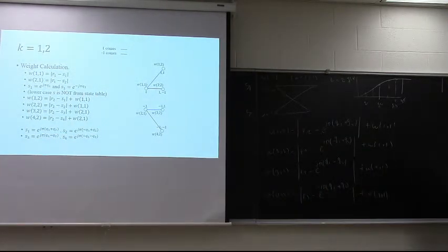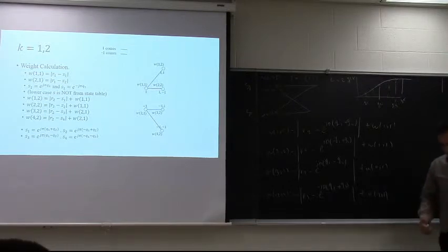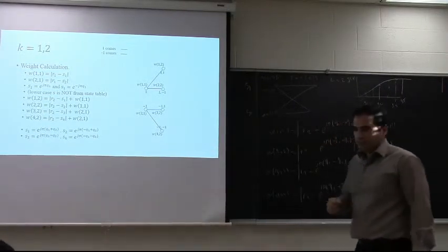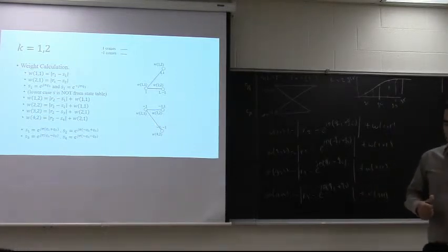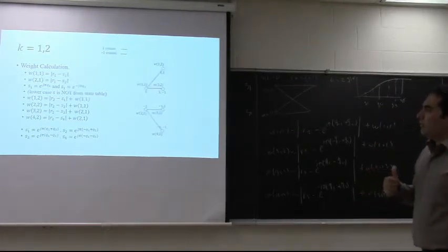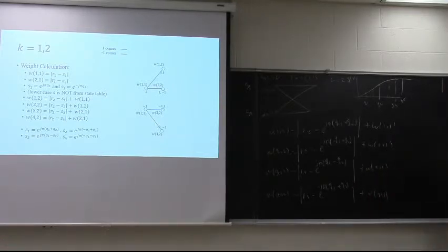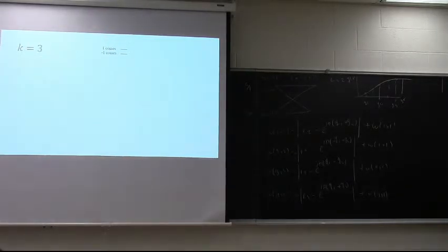This is the state diagram, state table for the complete GMSK signaling for the implementation of the receiver. You see that the uppercase S is something else. For K equal or greater than 5, you're using the state table. But before that, we need to go over somehow outside the loop, manually, whatever, because it's different.